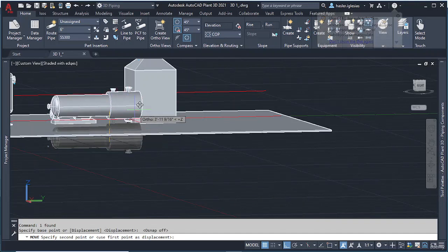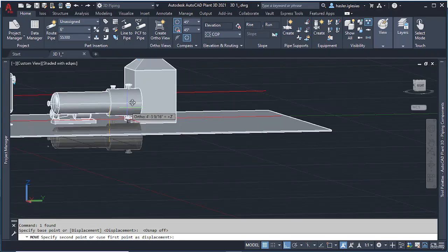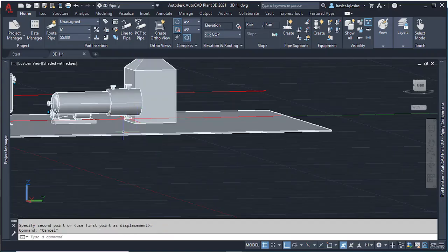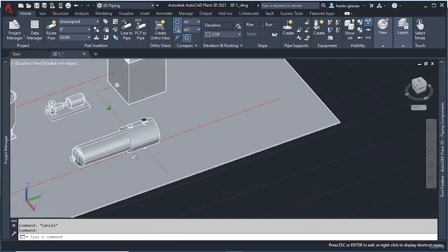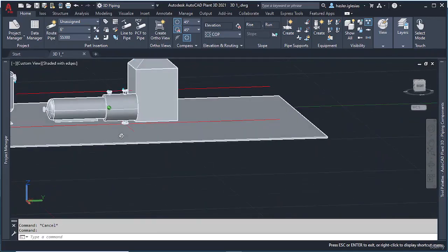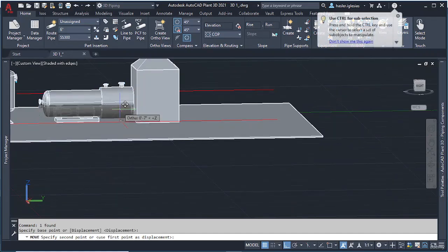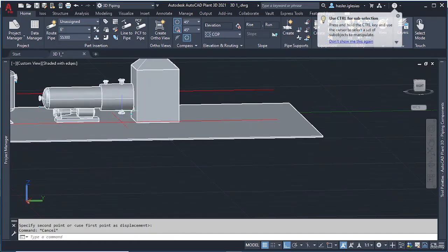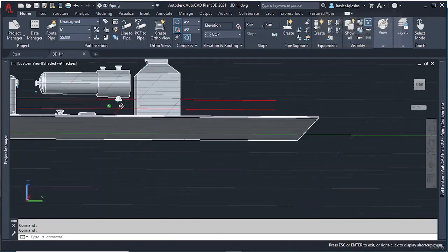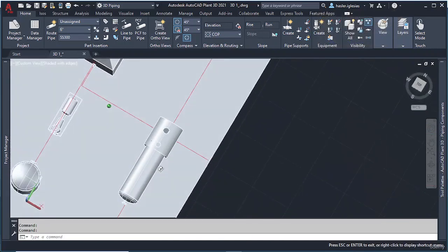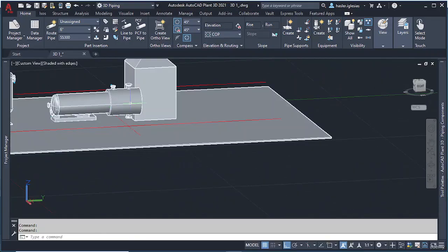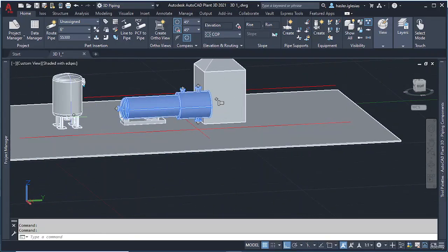Now look, in this case, it has a nozzle right here, okay? So I can't place it on the floor like that because I would be blocking a nozzle. So I have to put it higher there, and it cannot be floating. It needs something in order to work. And actually I have to move it a little higher because from the bottom nozzle will come out a pipe, and that pipe needs space, right? So I need to add some kind of support here, as we did with this tank and the legs.